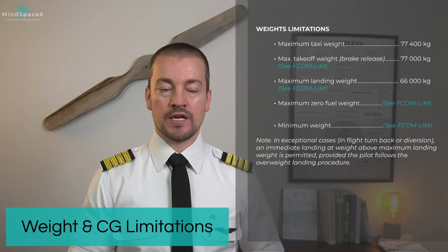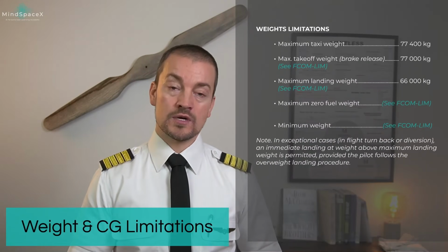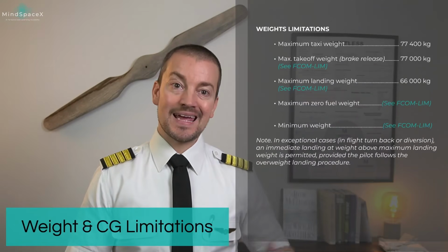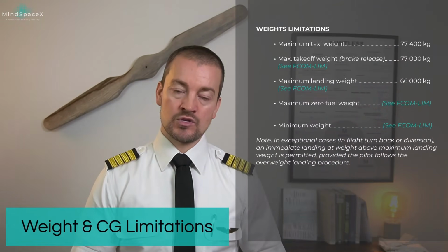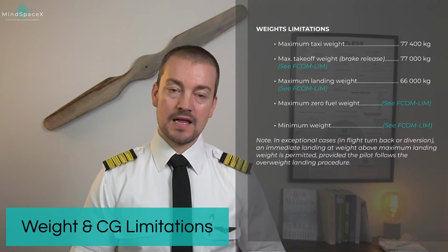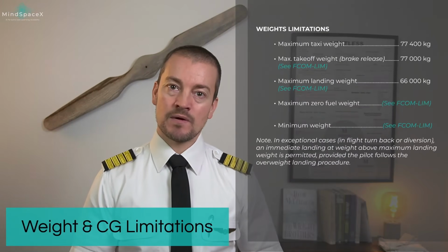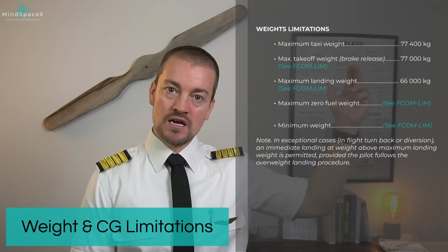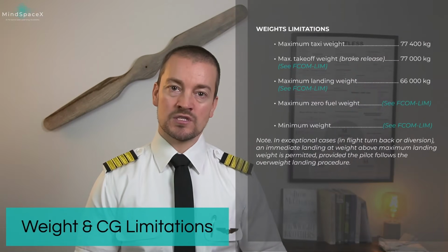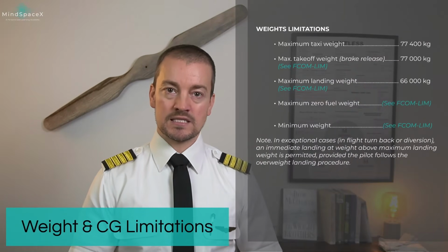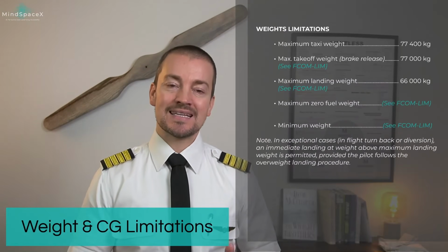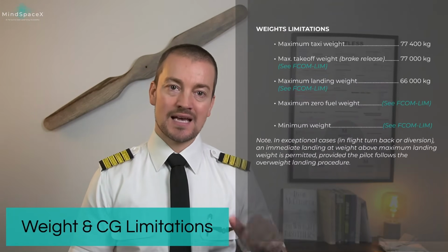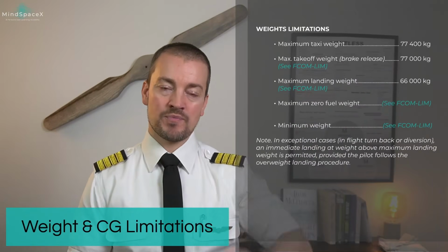Maximum taxi weight, also referred to as maximum ramp weight, is 77,400 kilograms in the A320. This is slightly above the maximum takeoff weight, as you can see here, which is 77,000 kilograms on brake release. This means we must be at 77 tons by the time we apply takeoff power with the